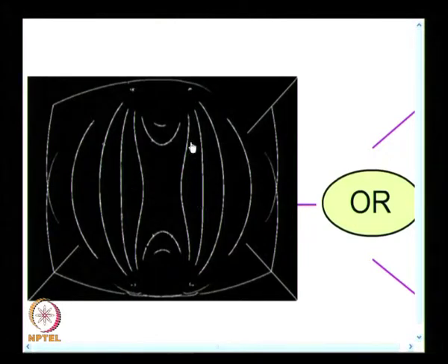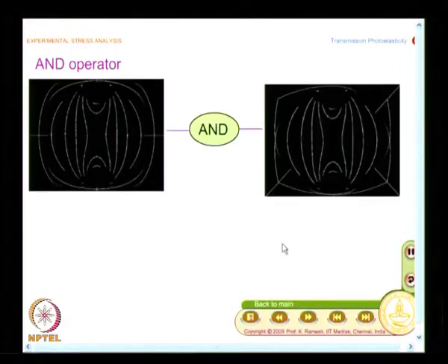And what you find here, the fringe skeleton is reasonably comprehensive and it has branches of noise, and in this zone you do not see much noise; in some other applications you will also see noise even in this, depending on the fringe orientation. The fringe orientation is a key point. So, in a very generic problem, 0 degree, 90 degree, 45 degree and 135 degree scans really help. Now, what I do is I do the AND operation of these two OR results, and that is what I am going to see here.